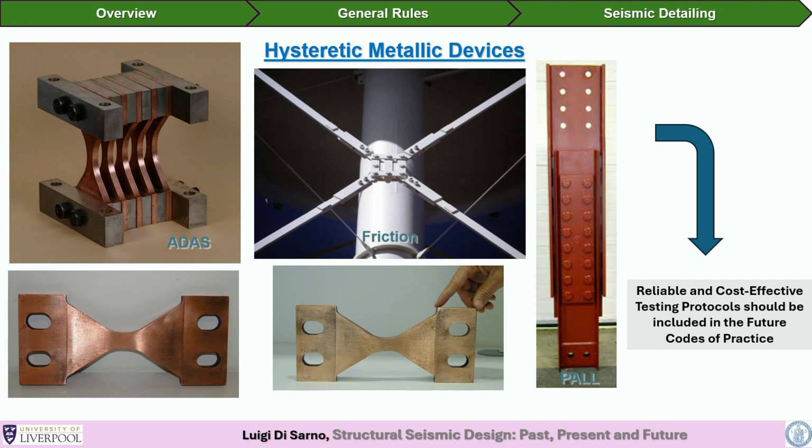Now, in terms of structural engineering, again, there are options that are available. For example, dissipation devices, like the one that you have in your car. If you go over a pothole, you don't feel all the vibration because there are dampers. These dampers can be made of any type of material. Here, for example, is shown a friction connection that will dissipate energy while the system is moving, so it's damping the vibration induced on the pole or any lateral brace of the system. This is brass that can dissipate energy when it is bent laterally, and these shapes are used, for example, at the intersection between braces, so that when the system is moving laterally, these elements on top will dissipate energy, hence controlling the lateral damage occurring.